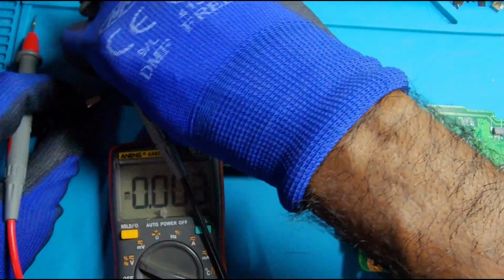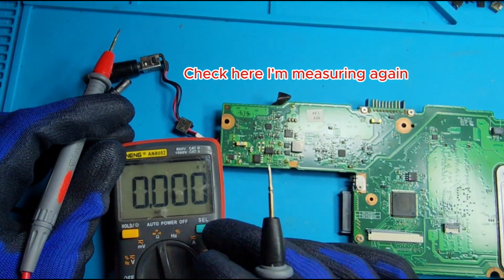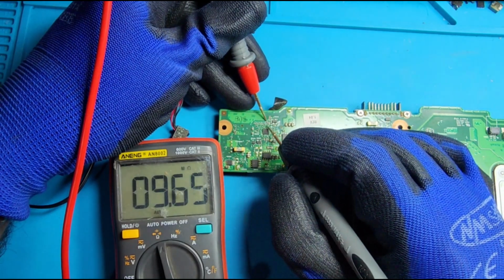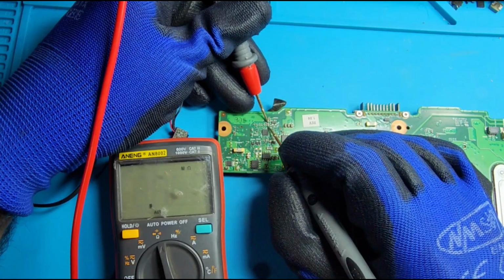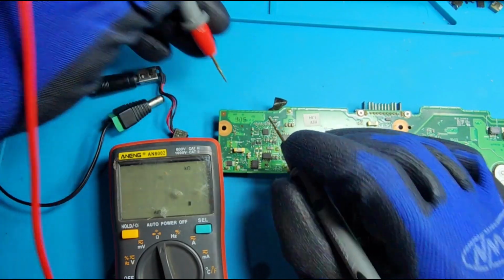Anyhow, let me measure the resistance value again in the resistors. The upper resistor, the R1 resistor, is 19.2 kilo ohms. The R2 resistor is 3.3, so the resistance value is appropriate.